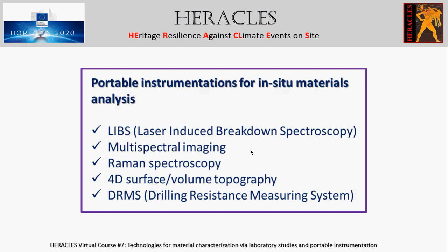And finally, the drilling resistance measuring system, which has two distinct aims: the evaluation of the current state of preservation of the stone, and the sampling of the drilling residue dust from distinctive interval depths for further physical-chemical analysis in the laboratory.